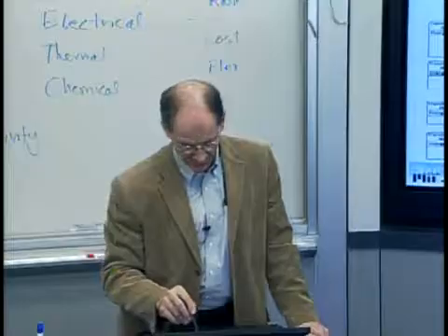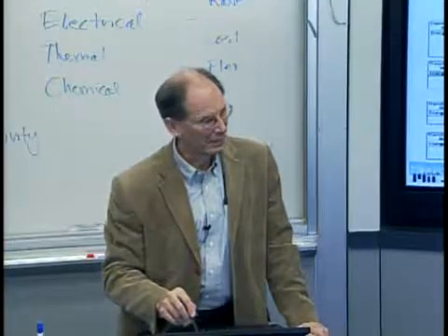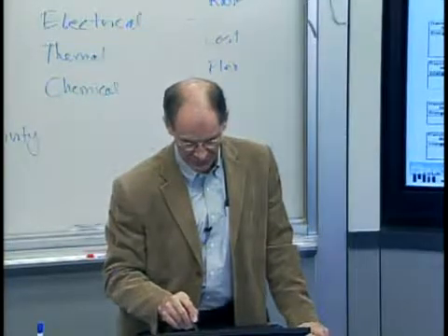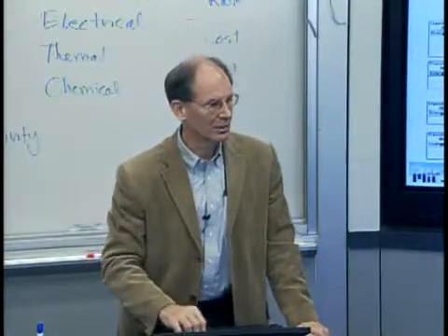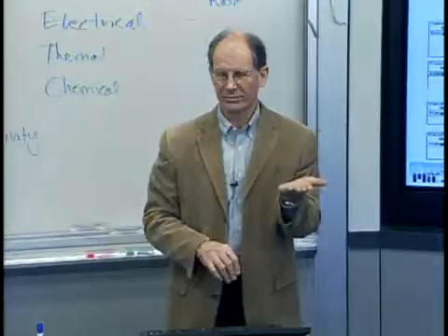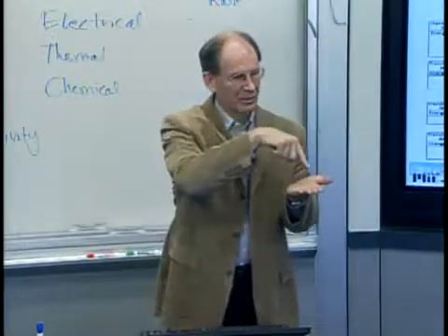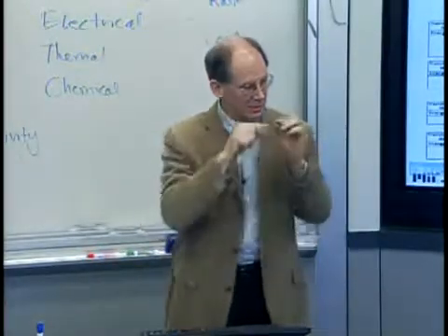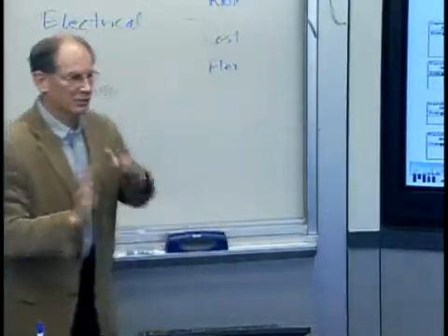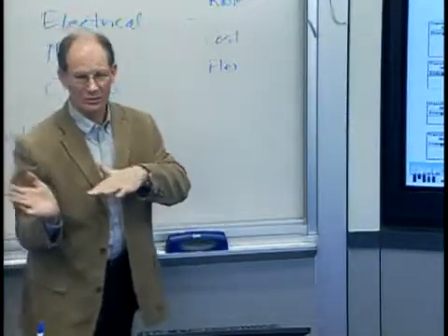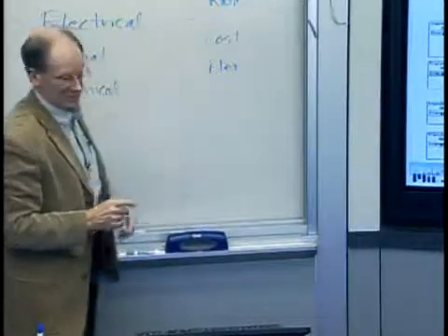There's also this: with powdered metals, you can sinter them thermally to get the shape. And when people decided they could sinter it locally with a laser, you could take a powder of metal and zap it with a laser and just get things to sinter to each other locally. So they changed the whole equation on how the process is controlled, which has effects on all these different things.